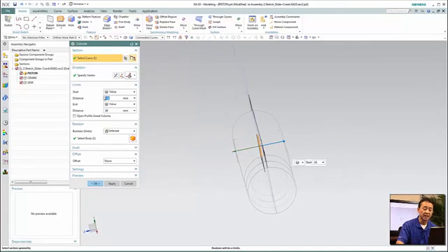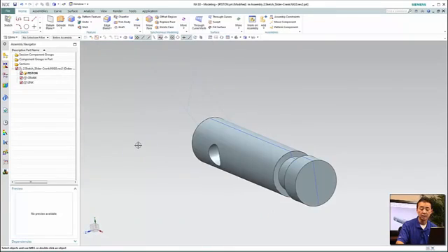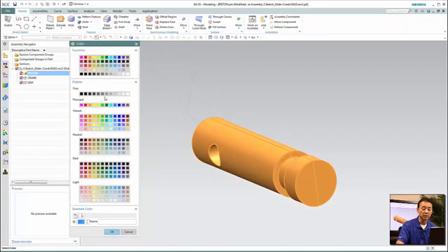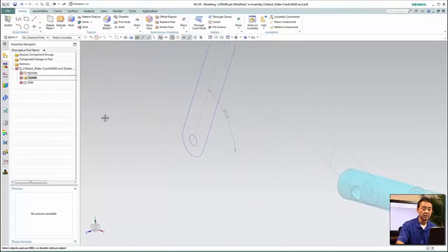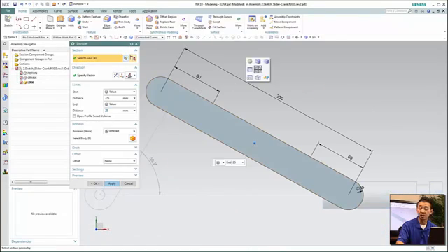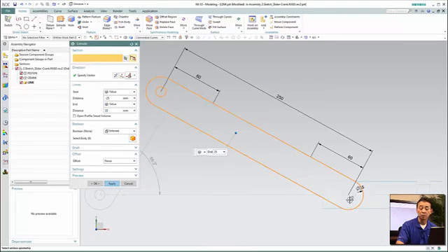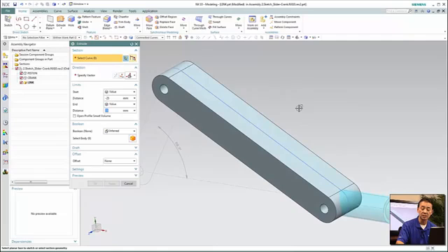So quickly we define a front-to value, or we can just go ahead and do a select-to on a particular face. We can do it either way. But nevertheless, we can quickly create this piston from the 2D layout. The next thing we want to do is work on a particular link. Same principle. In this case, instead of doing a revolve, we just do a simple extrude. Grabbing onto the sketch, we can take a certain distance.